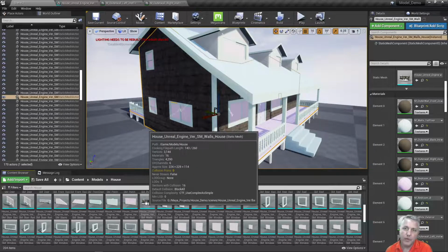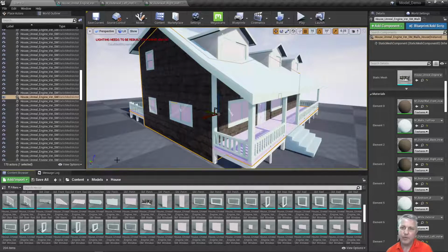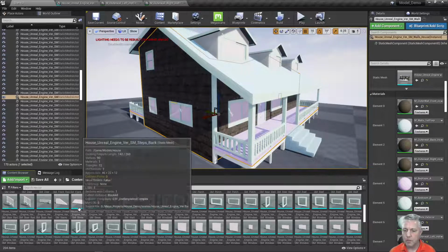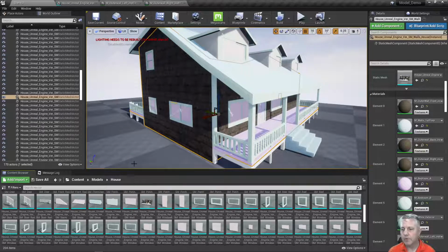And it's going to be saved that way, so if we ever exported it, these materials would go with it. Now, if this was not something you wanted to do, what you would do is apply them here to the house selected, and you would put them over here on the right-hand side, and that would only apply those materials to the house in the scene itself, not to the rest of the model, which would then keep this original blank look down here. So keep that in mind.